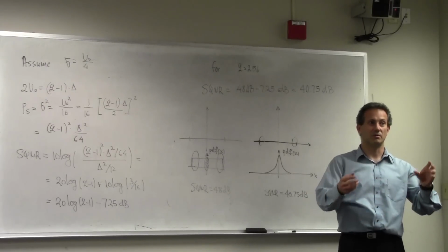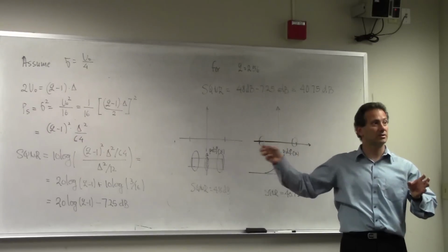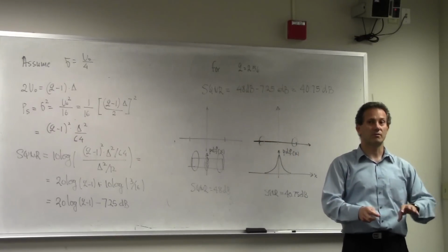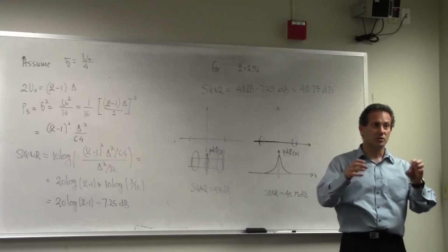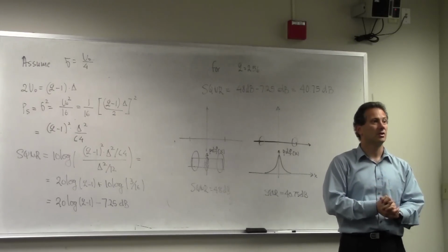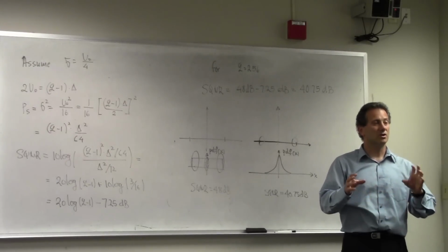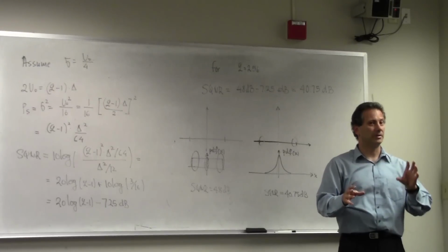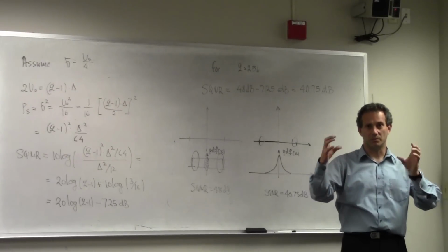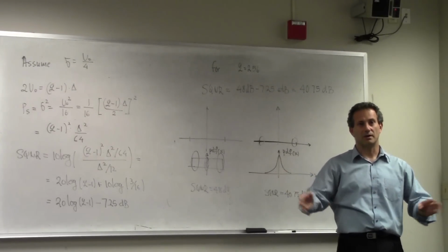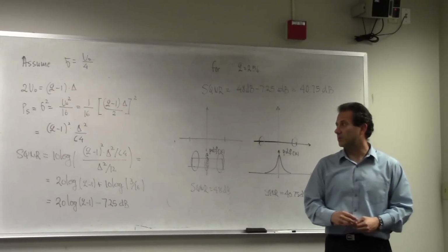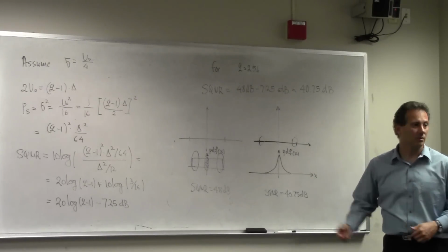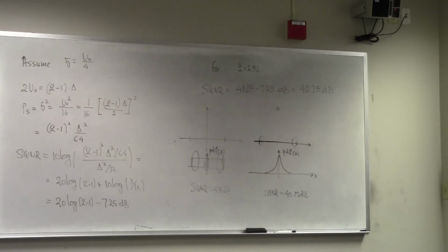You're gonna say, okay, this is voice, so let me pick this quantizer, and it's not gonna work for any other signal, right? So now your quantizer becomes tuned to particular properties of your input signal. That's not the way we like to build things in IC circuit design. We want to build one circuit and hit as large of a market as we possibly can. So we'll have to look at an alternative approach.